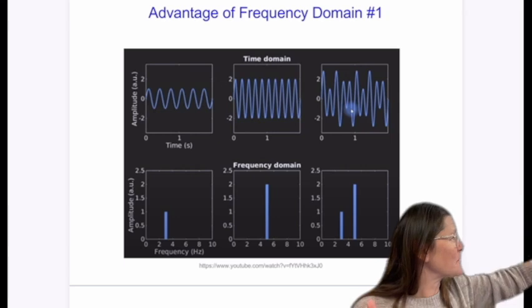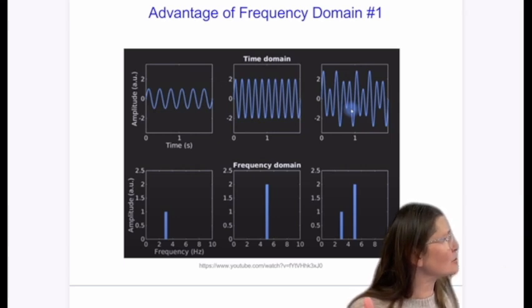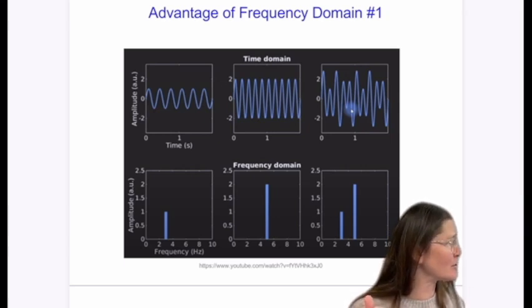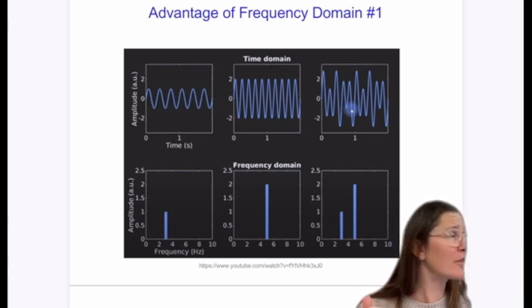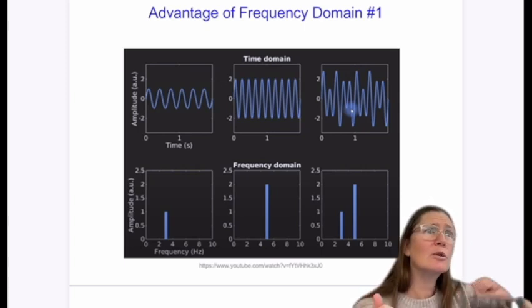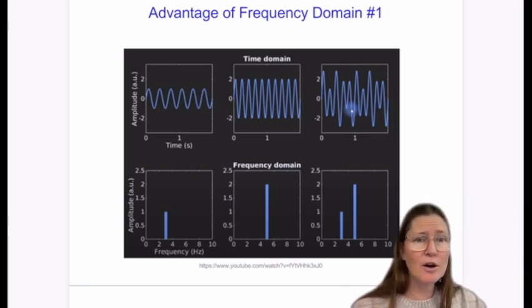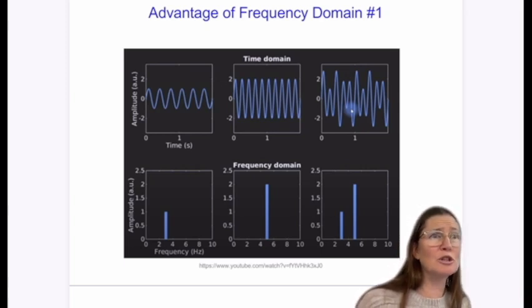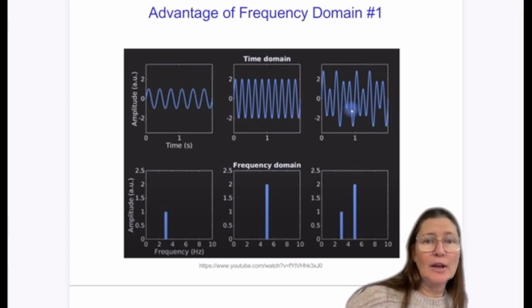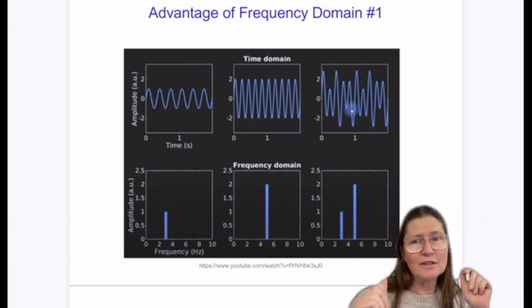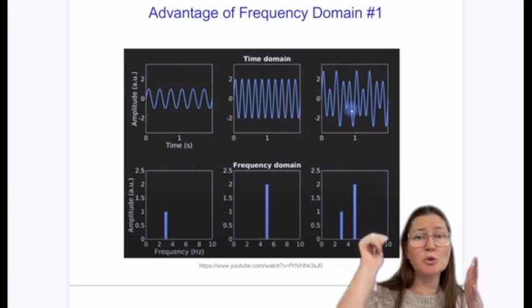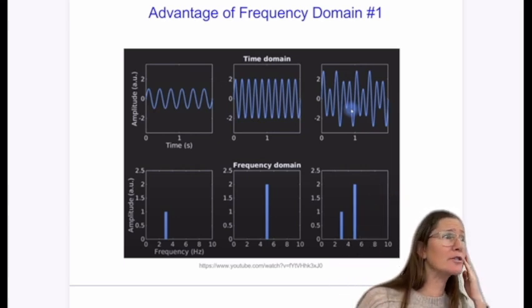oscilloscope. And then if we move to just the magnitude frequency plots of those, the first one would be described by this first graph, second one by the middle, and the third one just has the 2 peaks. It's really easy to look at this and say, oh yeah, at 3 hertz for the first one, that has the most contribution, that's exactly where the signal is. Same for the second. And then the third just shows you within this I have 2 main frequencies, and the higher one has more amplification in it or has higher signal in it.